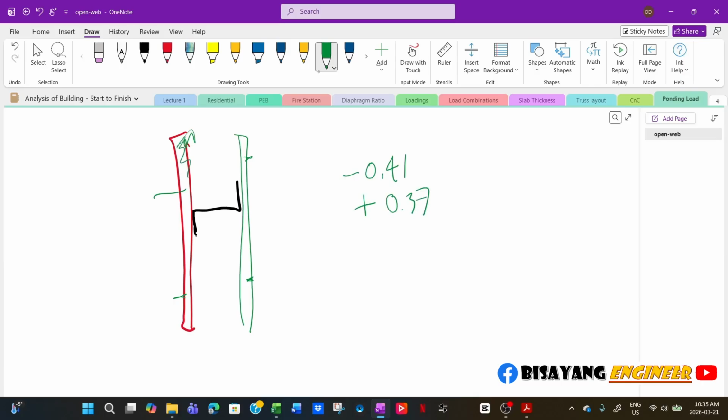So when you size or determine the thickness of this, the manufacturer will have a load table for their product. Say the spacing of the girt is, say, 5 feet.